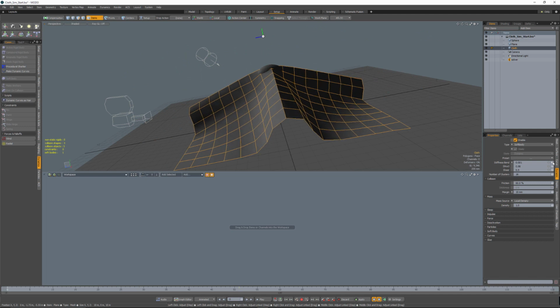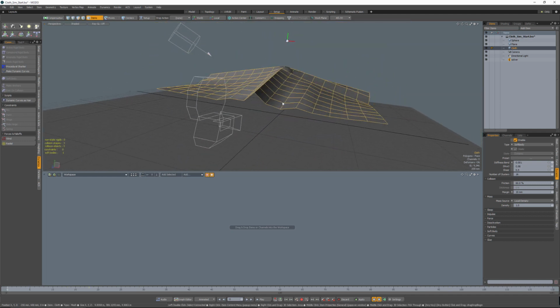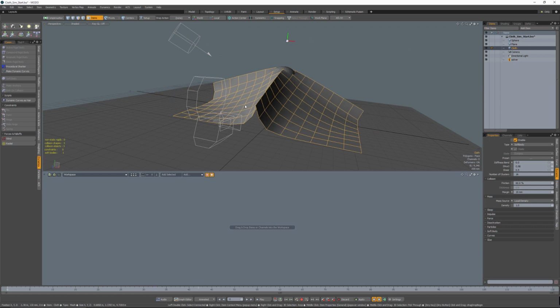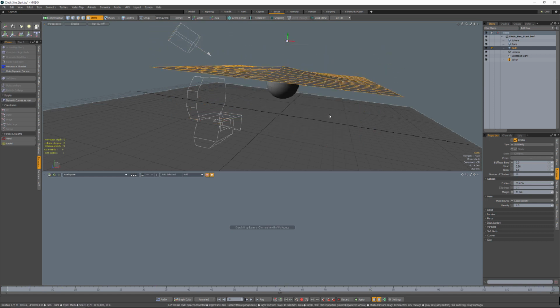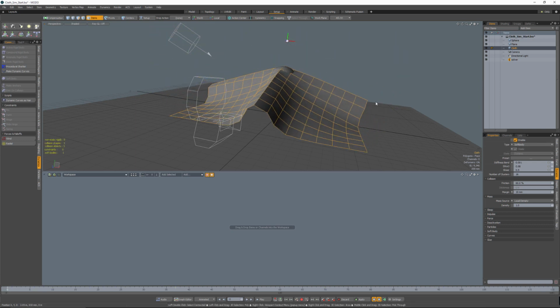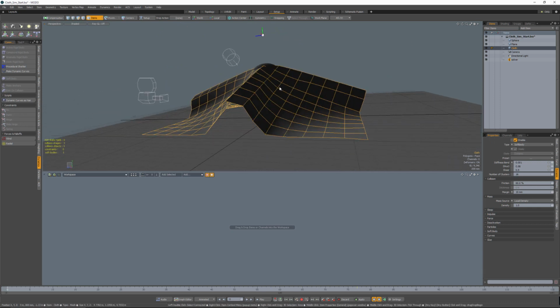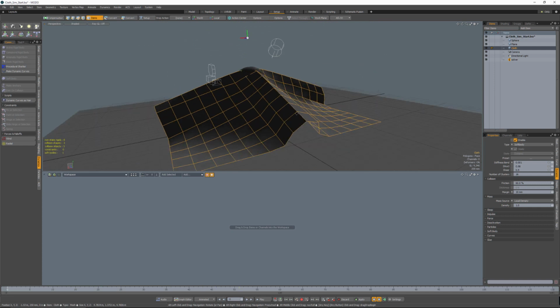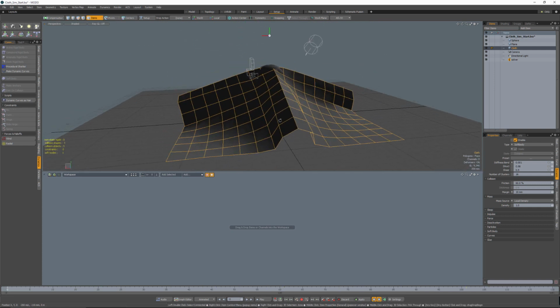So what I'm going to do is set this, even going up to 0.001, and we no longer get these pieces just collapsing into a V. So here's 0: you can see we go all the way down to a point here. And if we had more resolution and our other settings were lower, this part would start to cross over. So let's go up to 0.001. You can see we get a little bit of overall form to the object. That's going to be good, that's what we want there, and we may adjust that later.